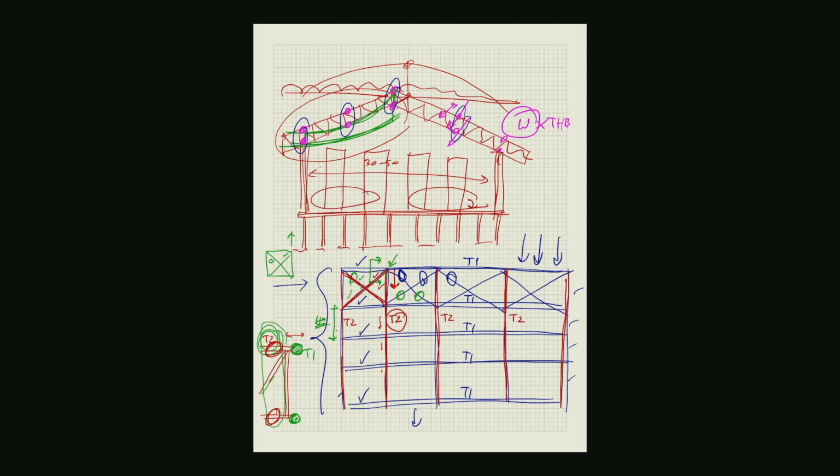The best way, maybe an even better way, is to make the 3D model. The 3D model will be more accurate, of course. So you put the 3D model of the roof truss and turn on second order analysis, right? Second order analysis, turn on nonlinear geometry. Nonlinear geometry is turned on, and then you put in the brace stiffness that is guided by the AISC specification. So you put it in, and then you check.